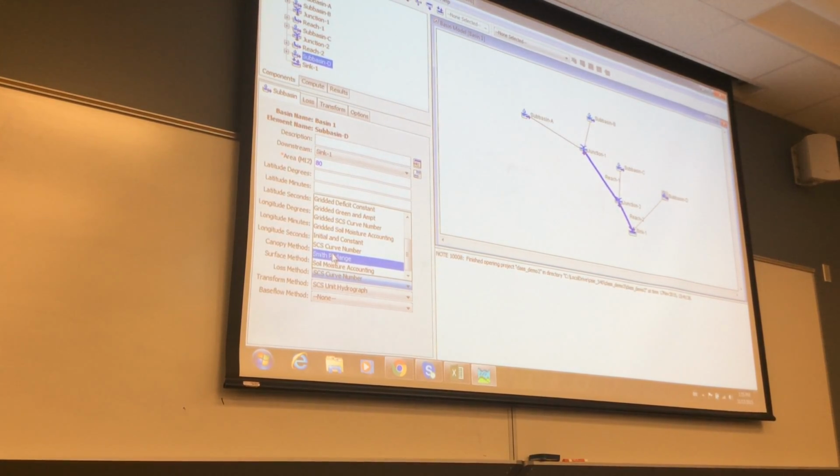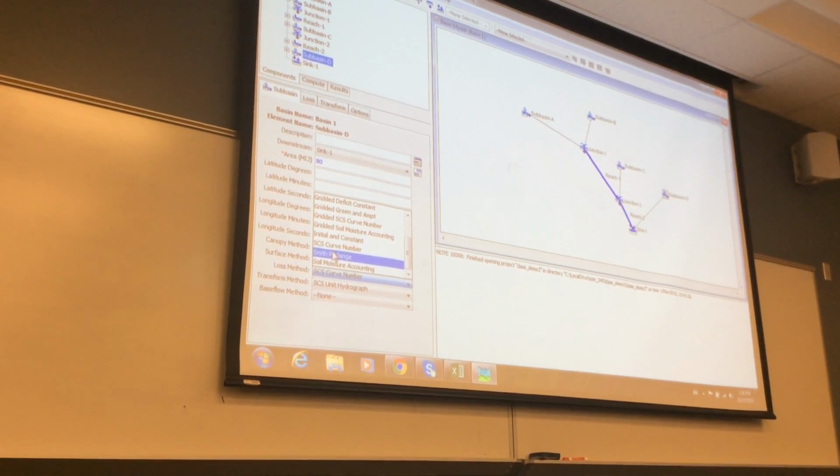That is different though. What that is doing is cutting your watershed here and saying 20% is completely impervious, and then I'm applying the curve number to the rest of it. In the table, it's giving you some guidance to choose a good curve number that represents the overall thing. Does it make sense? Okay, so be careful with that.